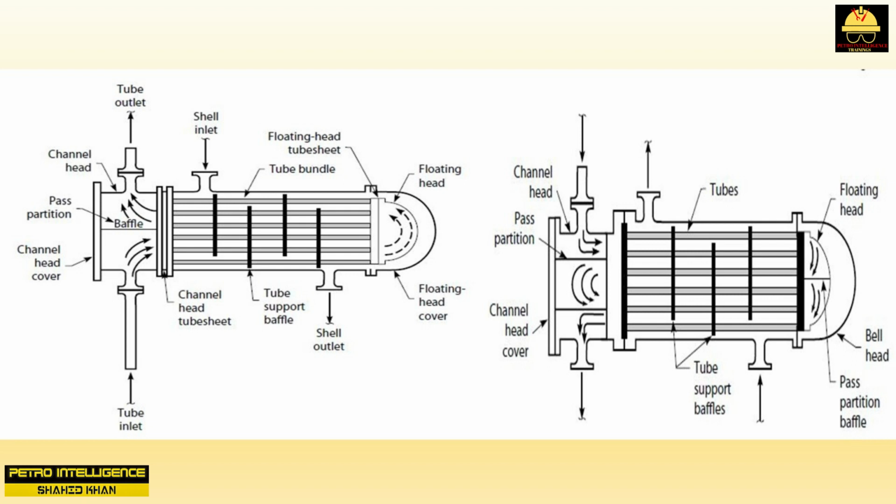Quite likely, even after several years of operation, the pressure drop of a 4-pass exchanger will be greater than the delta P of a 2-pass exchanger in the same service. Quite likely, the initial U value of a 4-pass exchanger, days after it has been returned to service, will be only slightly higher than the U value of a 2-pass exchanger. However, the 4-pass exchanger will maintain its U value with time, far better than will the lower velocity 2-pass tube bundle heat exchanger.